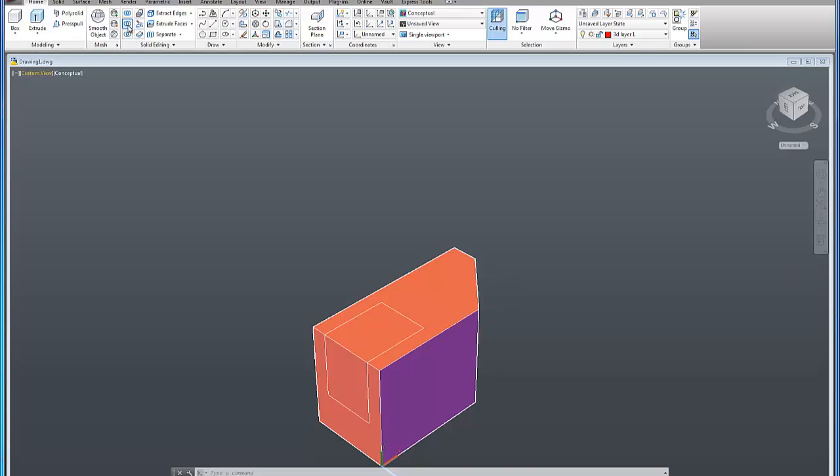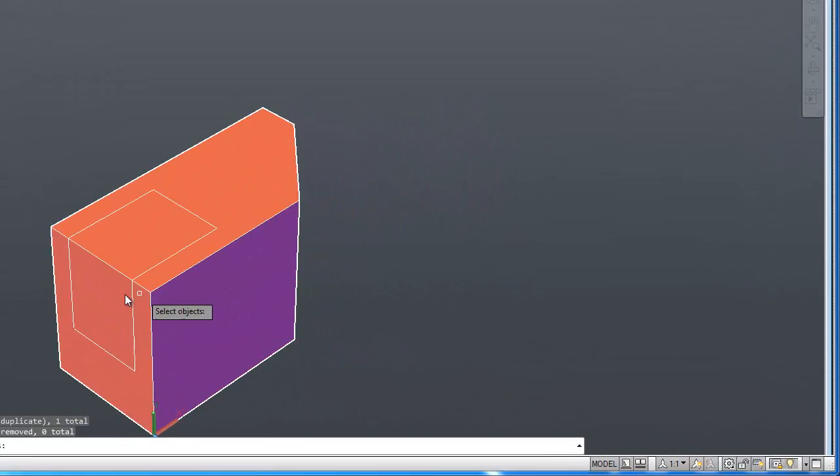So now we need to do the subtract command. And right here under solids editing are where some of the feature capabilities are that you can explore. And the 3 that are in a stack right here include unionization, subtraction, and intersection between the object shapes. So I'm going to choose subtraction. When you subtract objects, it's going to ask you to select the original object, or the object you want to keep first. So I'm going to select my keeping object first, which is the big shape. I right mouse click and select the object that I need to subtract, which is the smaller object, which is embedded. And I just selected the same object twice.